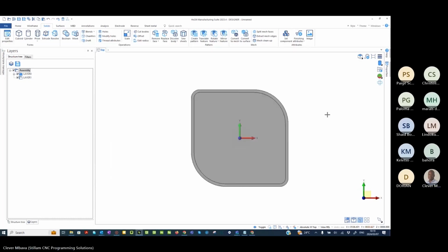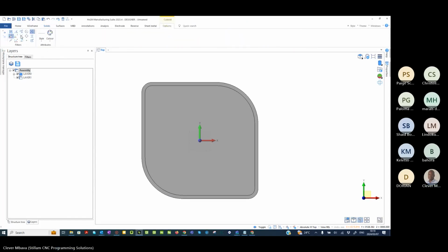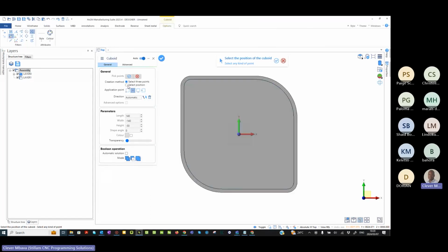All right. Then I need to quickly bisect this into half, not really to bisect it, but I need to design a certain feature within the part. So I can go to my cuboid again. Instead of dynamically designing the shape, I can pre-give it the size that I want. Say in here, I would like to make it 200, which is the length. And the width of this one, I need to make it 8 millimeter. I can probably make this one minus 10 millimeter on that.